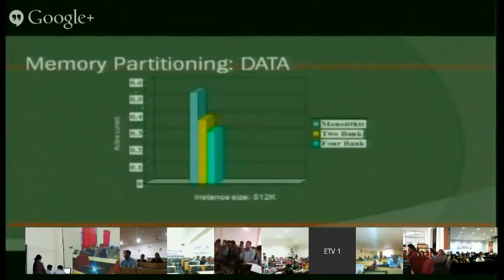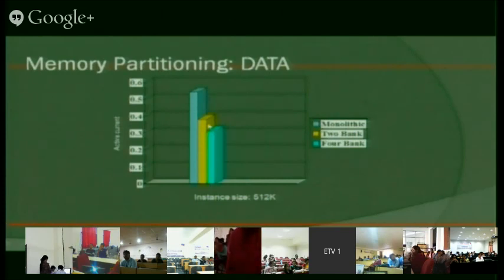So this side is active current, but you can see the height of this. The first one is, as I told, the complete one, 512 by 512. So it consumes this much power. It takes current which is 0.6 here, 0.6 amperes. Then if I make 2 banks, it becomes 0.4. This yellow one becomes 0.4. And if I make 4 banks, it is further reduced. If I make 8 banks, you can see from here to here is a massive reduction, but here to here it is not much, and from 4 to 8 maybe there will not be much reduction also.